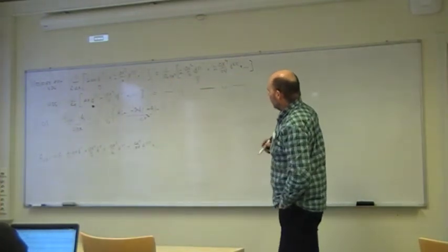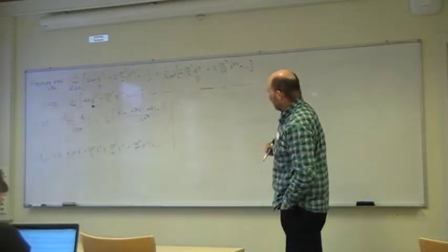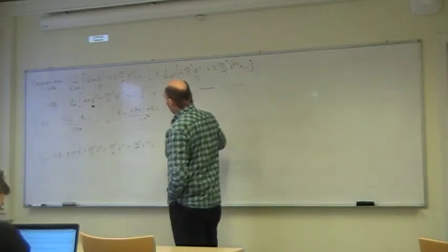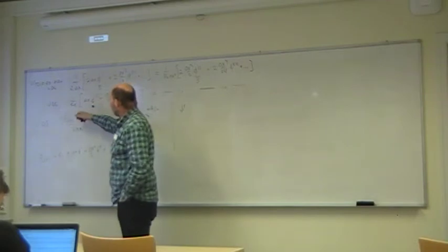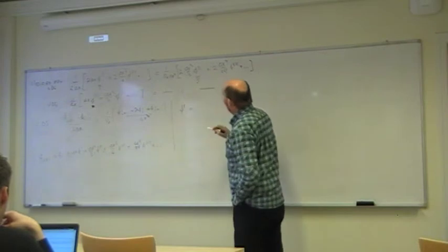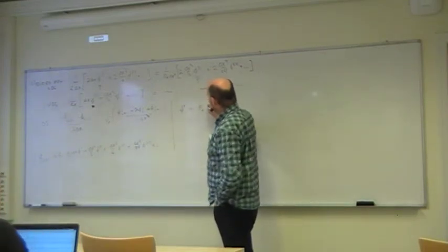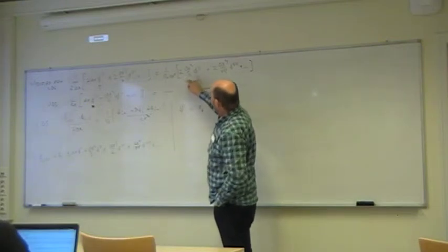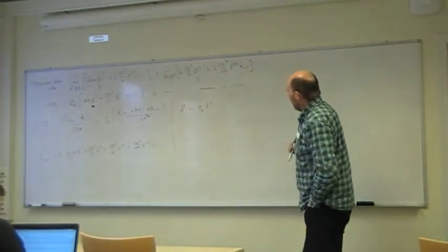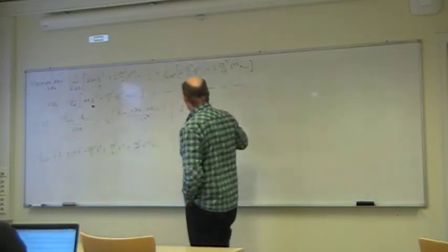And now if you rewrite this one, the UDS scheme, you can now write it in the form, the derivative here, just multiplying in, equals, and what do we have on the other side? Well, we have 1 over the Péclet number, and here I will have the double derivative, and now I will have something else with the double derivative.